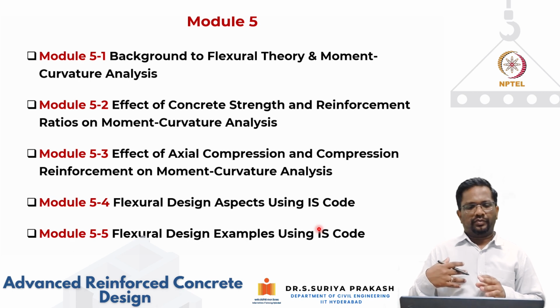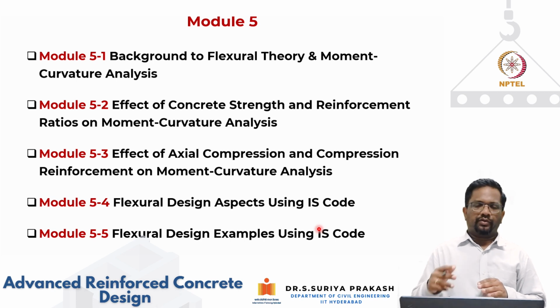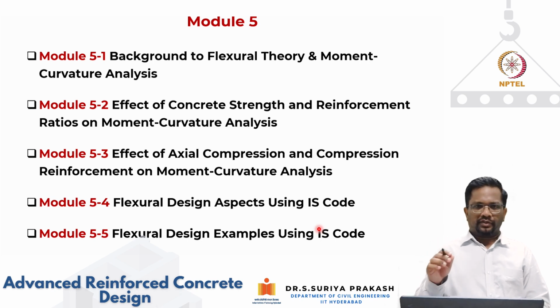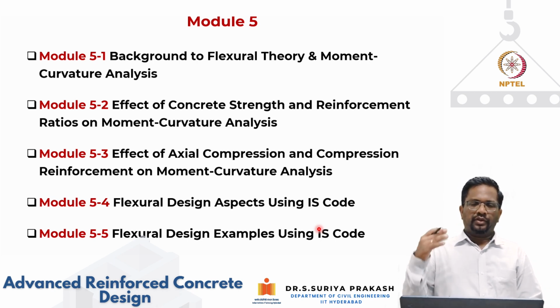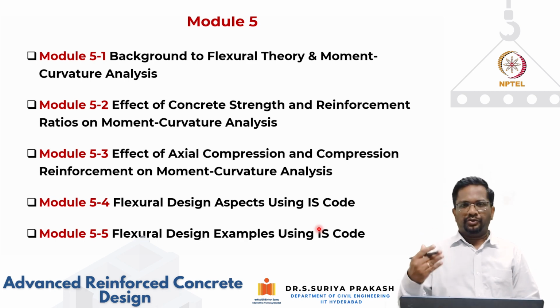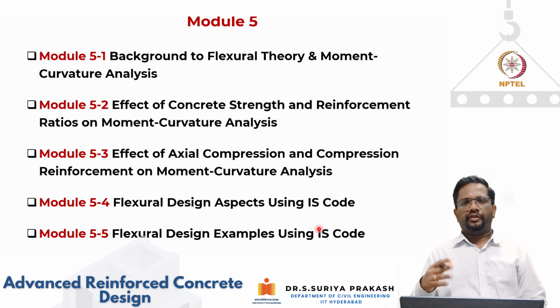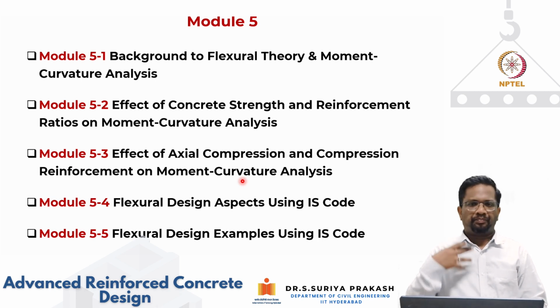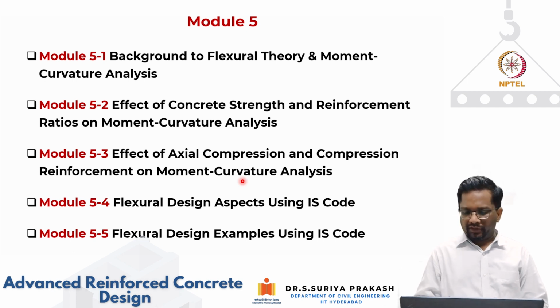In the next two parts, that is module 5.4 and module 5.5, we are going to use the design stress strain curve that is specified by the IS code. As we have discussed in the material chapter, the IS code provisions use design stress strain curves which are factored. They use less strength, and the constitutive equations are different from what we get when we test concrete cylinders, just to ensure that we predict the strength and other parameters in a conservative way. The code is using the design stress strain curve.